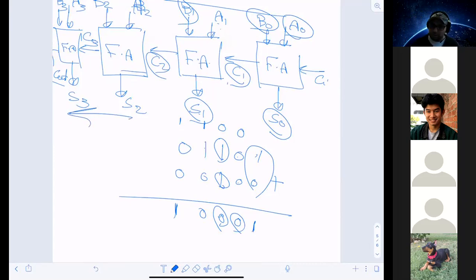Yes. Okay, so now we have a circuit that is actually adding, right? Everybody agree? It's not completely adding, you know why? Because if you notice, the first stage is not a full adder. The first stage is a half adder. That's why you have the carry in, which has to be 0. The upper half of a full adder is a half adder, right? That makes sense?